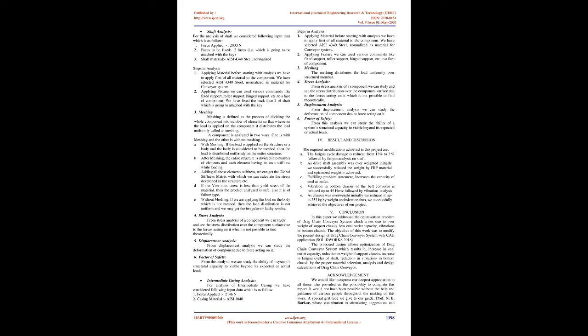Advantages of FEA. 1. According to strength of materials, the stress in a body is assumed to be uniform, but in reality it is distributed. This can be shown by the finite element method. 2. It can solve models having complex geometry and show the stress concentrated areas. 3. It helps the design engineer to optimize the model before fabrication, hence saving time and money. Multi-purpose analysis is also possible due to FEA.